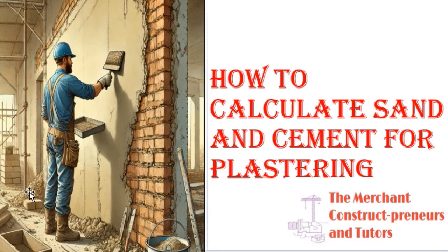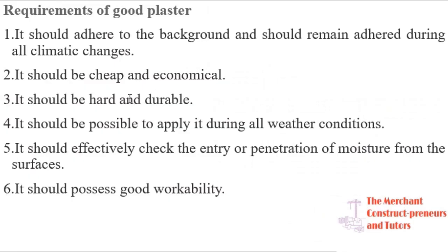So one thing to preserve the plaster you are using: on the surface where he's standing, you can place a DPM material, a thick nylon, so that once he's plastering, the excess plaster falls onto it. You can then take it while it is still workable, remix it and use it to plaster the wall. So it makes it easier and cheaper. Hope you understand this. So let's move on to the next one.